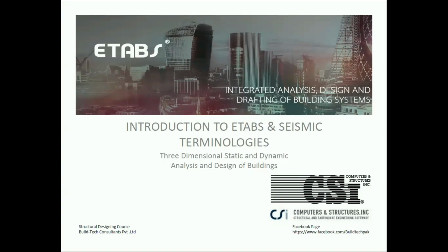So first of all, the product is from the CSI company, and they have various products for building design and other structural members, like this particular software, ETABS. It is particularly for building design. It is a frame structure software, so you are able to design beams and columns. And nowadays, because they have made many modifications from previous versions, like 9.7.4 and other versions, you are not able to calculate the footings and slabs there. So CSI has a different product for that.